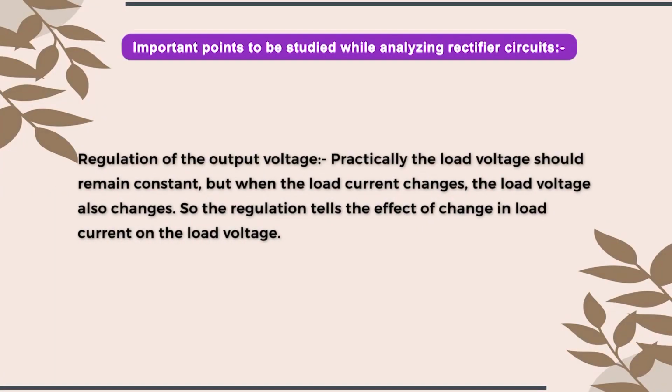The second parameter is regulation of the output voltage. Practically, the load voltage should remain constant, but when the load current changes, the load voltage also changes. So, the regulation tells the effect of change in load current on the load voltage.